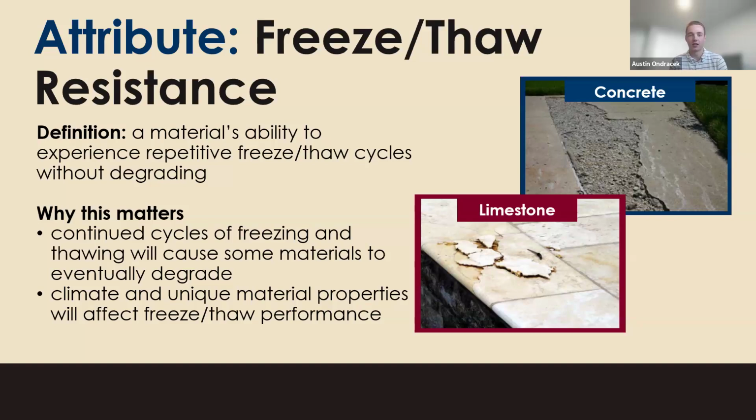In this case, is it a limestone that's maybe a West Texas limestone or a chalkier limestone that hasn't gone through as much of a freeze thaw cycle and is more likely to be susceptible to it? Or is it a harder grade Indiana limestone that is more likely to just do fine through proper maintenance and care? Both can have susceptibility to freeze thaw degrading over time. It's just making sure that we understand that natural stones are susceptible as man-made, but overall, a natural stone will perform much better in a freeze thaw climate, especially when installed in the climate that it is quarried from and manufactured from.